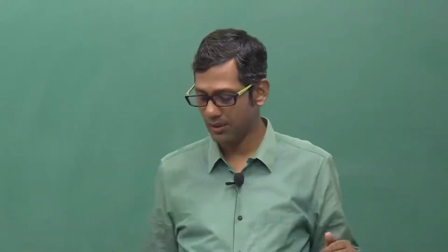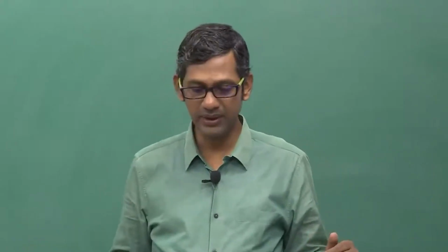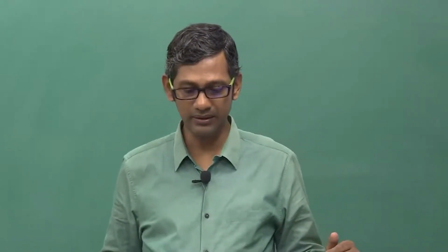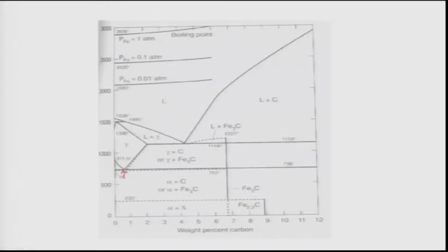Okay. Or if you want, let me just go back to the phase diagram and explain again. Here it is. So suppose I take about 0.6% carbon steel, and I directly quench from 950 here to 400 degrees Celsius here. It should transform into proeutectoid alpha ferrite and pearlite, as you have seen in the microstructure. But if we cool it slowly, then only it can happen that way.